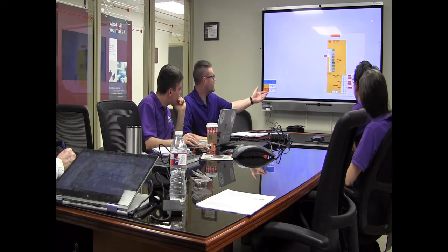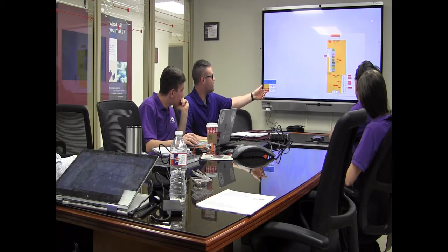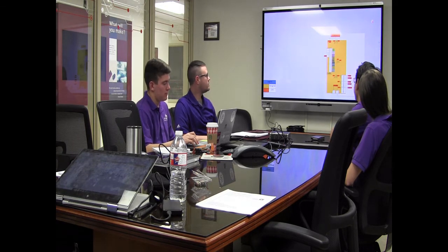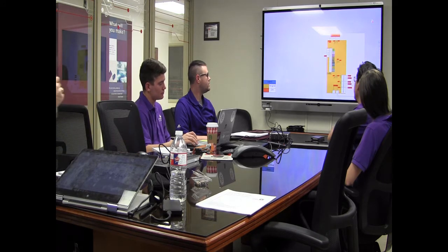So yeah, we have the Wyze Cam that's connected. It has an 802.11 connection to the hotspot that we'll see in a second. The PCA 9685 is a 16-channel PWM controller that speaks I2C up to our CC3200.